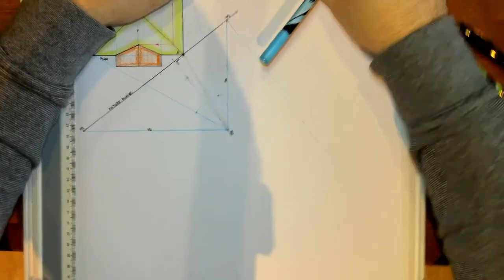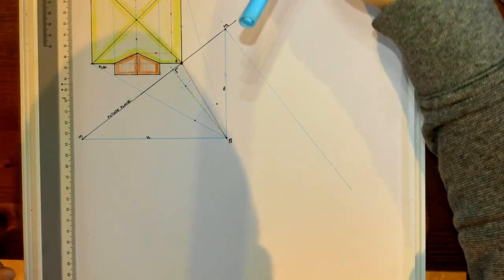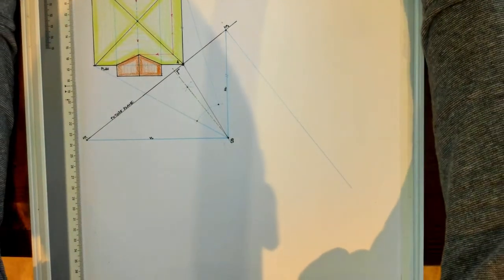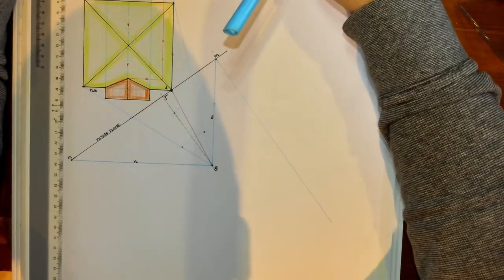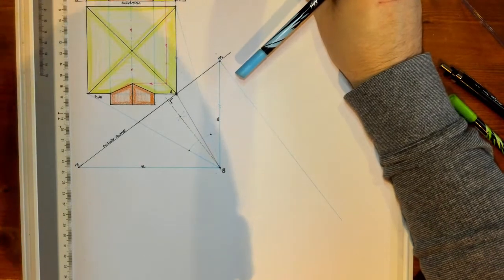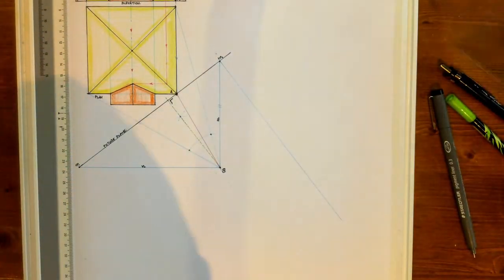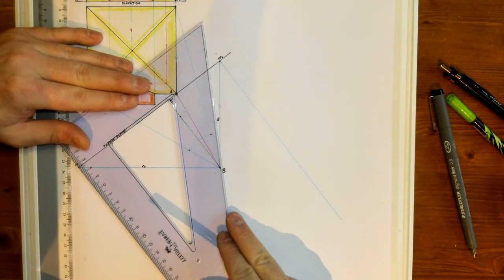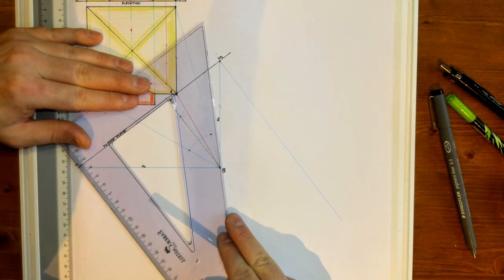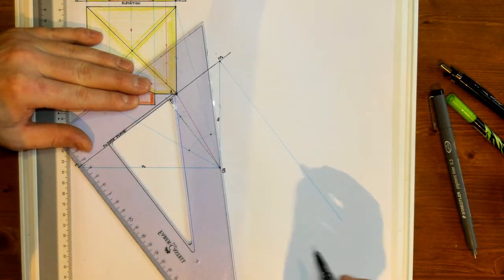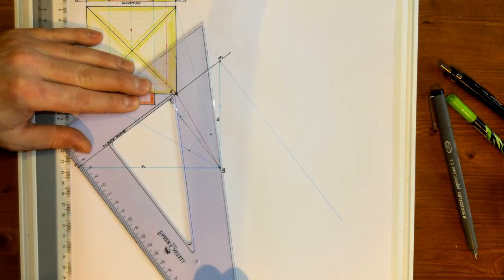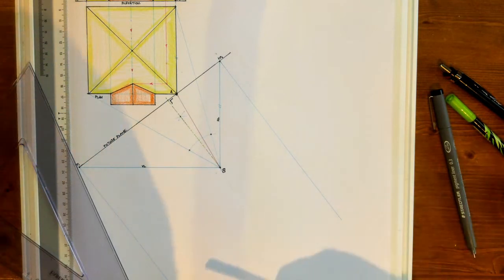Okay, we'll kind of forget about the elevation for the moment. We'll jump back up there in a few moments when we need to. Okay, so apologies about the moving around. I just want to get the full plan view in there if I can. Yeah, okay. And likewise here now, I'm going to go from, again, line up with the outside, line up the inside line of the set square there. Of course you could use a protractor as well if you wanted to, or you could use sliding set squares from the line you created on the other side, and just draw that on. Again, don't worry about the length of it.